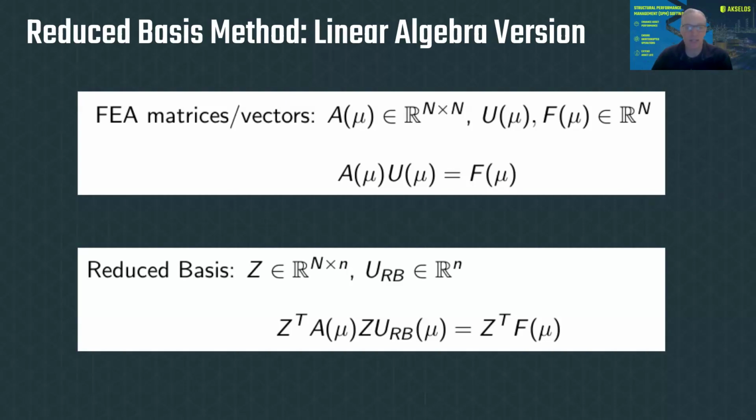And the tricky part is not this. The tricky part is, well, what are the basis functions? You have to have a good way to pick these basis functions so that they are representative of the solutions you're trying to reproduce over the parameter range you're interested in.